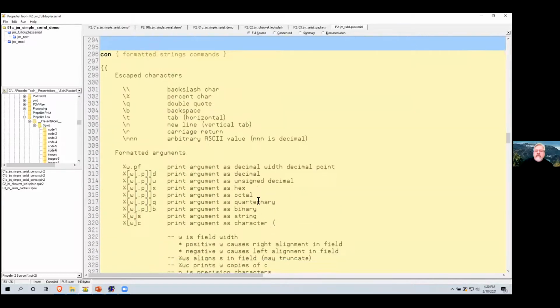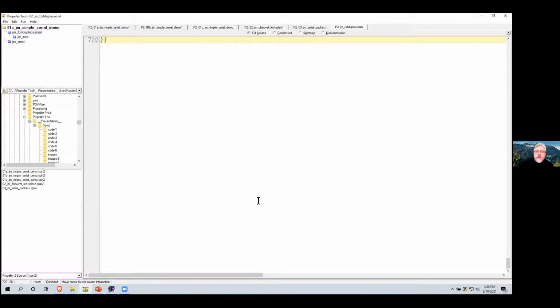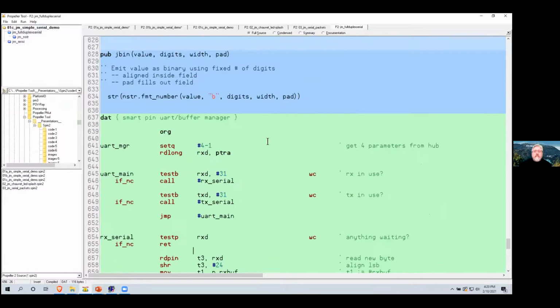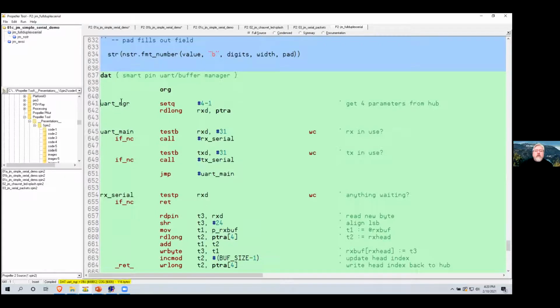If we go down to the assembly portion, again, this is really fairly straightforward stuff. So here, and you notice I'm calling it UART manager. They're not UARTs, they're where the pins are the UARTs, so this is just managing them. So what I do first, since the configuration passes the pin numbers along, this little chunk here looks to see if the pin is negative, a negative value. It's looking at the sign bit in the pin. If it is, then it ignores it.